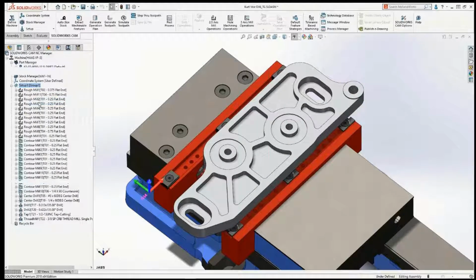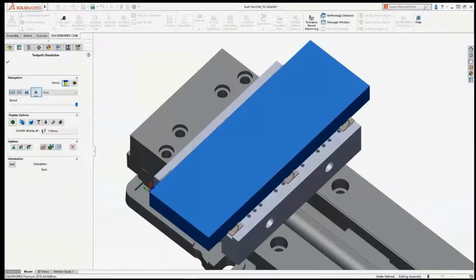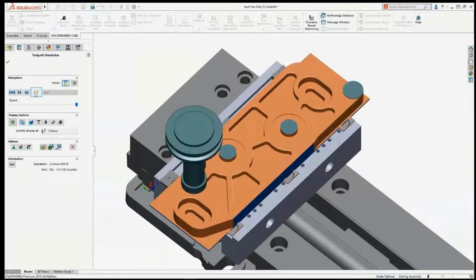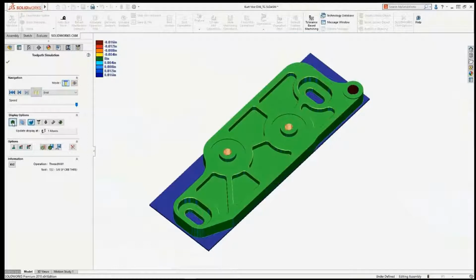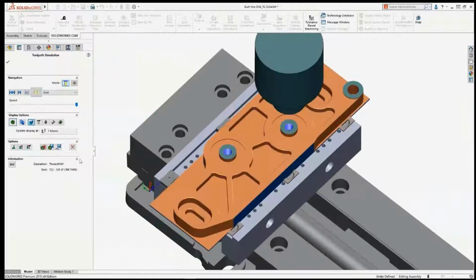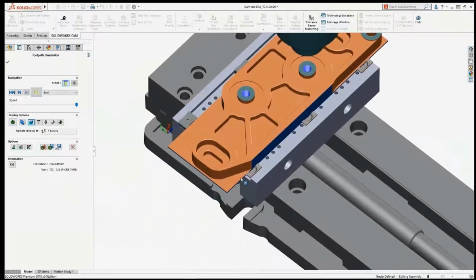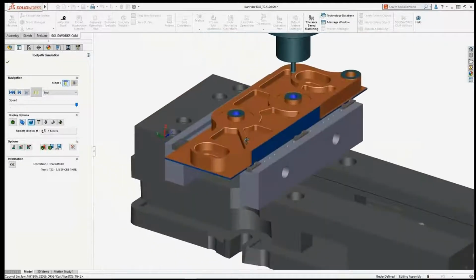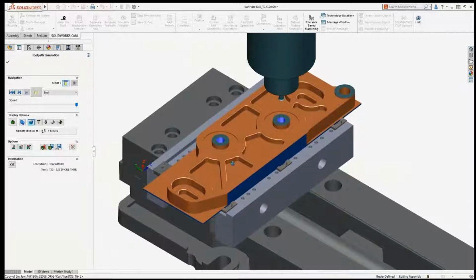After we have done some optimization to the toolpath, let's simulate the motion, and don't forget to compare the results. The final machined part is giving acceptable results, except for the lower side of the workpiece, because it's mounted to the vise and we need to make another operation with the part flipped.